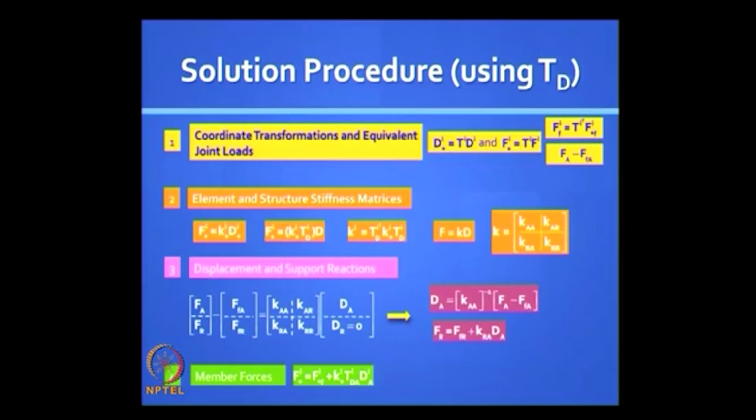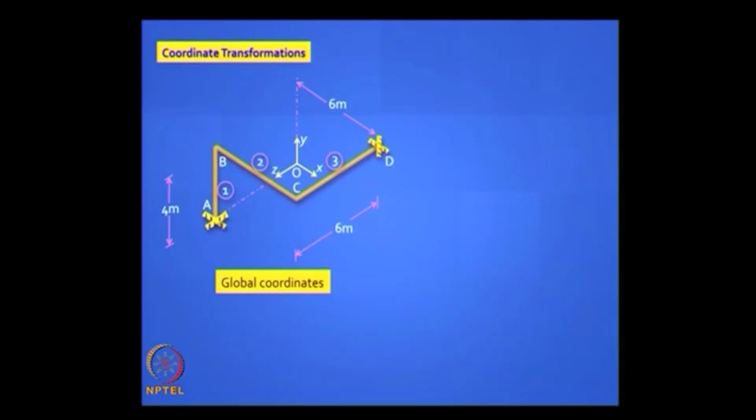Luckily we don't have any support settlements, we don't have any indirect loading. Okay, so first we have to mark the coordinates. How many active degrees of freedom do you think we have? Active degrees. You will have active at B. How many at B you will have? 6. Let's take a look. 6. And look how nicely we've oriented them along the global x, y, z axis, and the colors: we've nicely put the green color for translations and, what color is that, pinkish color for the rotations.